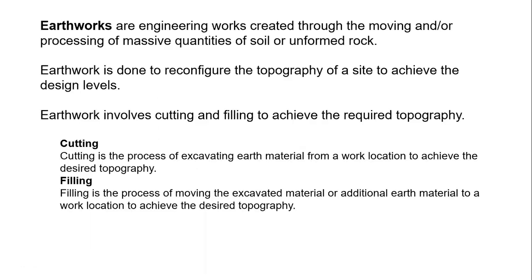So earthworks are considered engineering works created through moving or processing massive quantities of soil or unformed rock. This is done by reconfiguring the topography in a site to achieve the design level. So it involves cutting and filling to achieve the desired topography. Of course, cutting can be defined as the excavating of earth materials from a work location to achieve a desired topography, while filling is the process of moving the excavated material or additional earth material to a work location to achieve the desired topography.